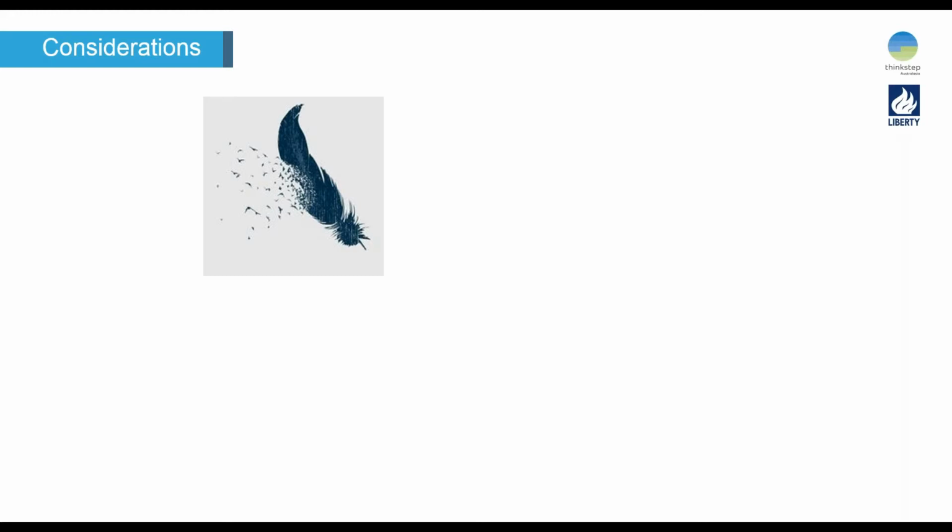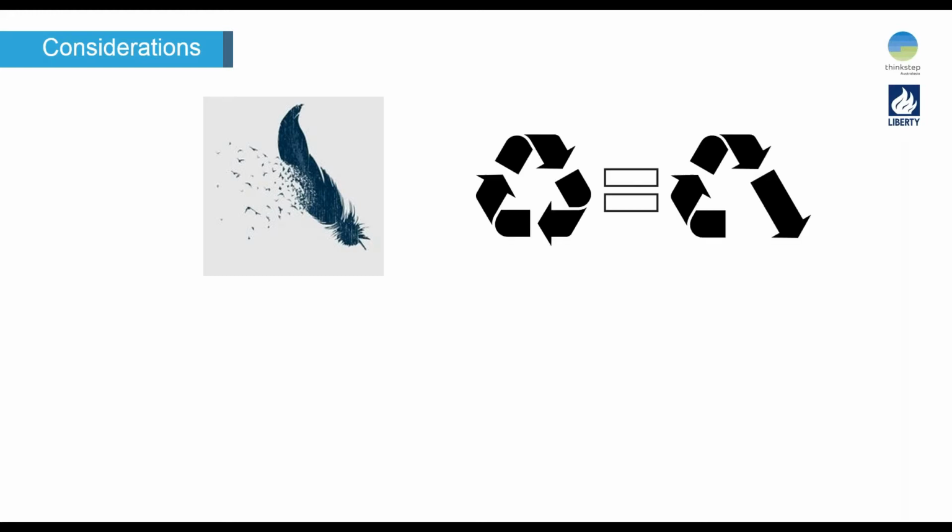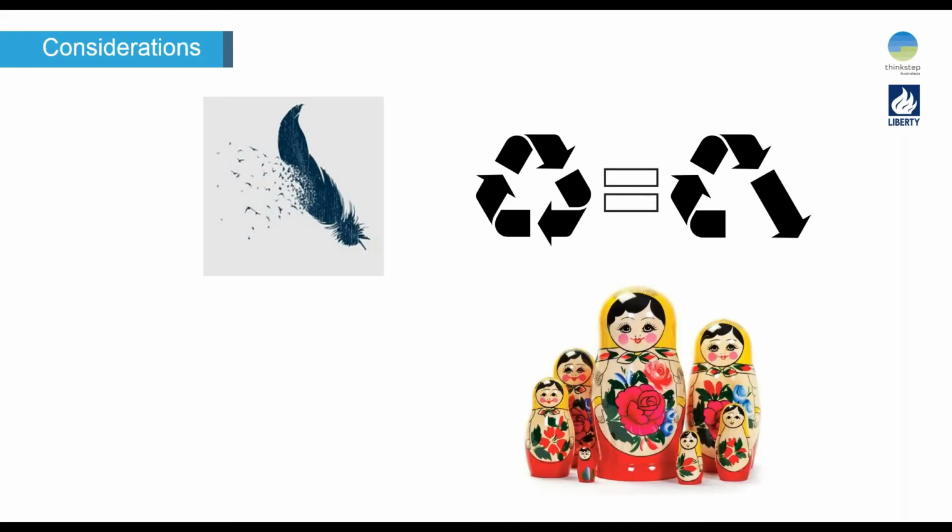Sometimes you have, for instance, higher strength concrete but less of it, or more reinforcing steel in order to manage it. So while the Material Circularity Indicator distinguishes between reuse and recycling, it then treats all forms of recycling as equal. It's not really that simple, as we know. We know that it's important to keep materials at the highest value and to consider the beneficial aspects of materials at each life cycle, as well as their long-term impact. So material circularity basically says, oh, it's been recycled, maybe it's been downgraded, but that counts. So that's something to think about in terms of putting it to use.